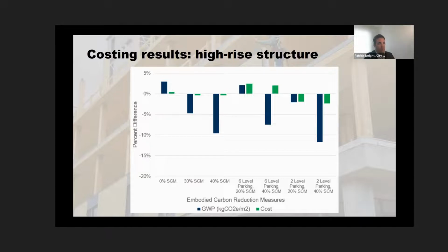One of the things we have genuinely heard is that cement can be one of the most expensive parts of concrete, and reducing cement can potentially save costs. That is what was reflected here in the first 3 bars on the left. The baseline in this case was assumed to be not 0% SCMs, but actually the first step in, which was labeled 20% SCMs. So we weren't just using the worst concrete as the baseline, but there was still potential for reductions beyond that and potential cost savings as reported by the costing consultant.